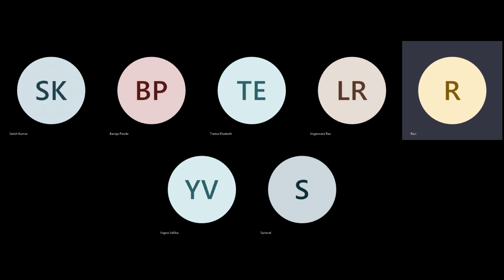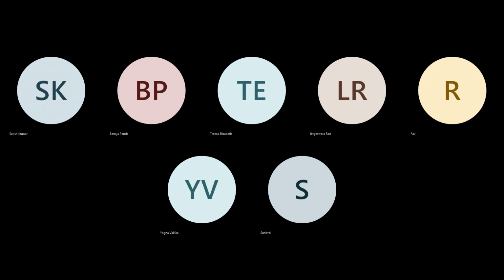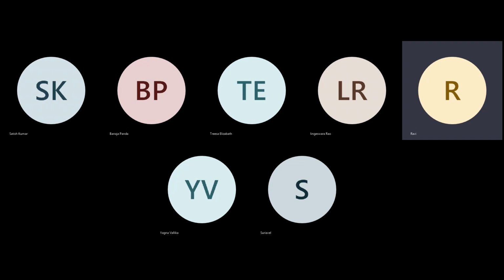Manhattan means exactly between this point and this point, how much is my rectangular distance? That's the Manhattan distance. Your route can go all around the place, but that is a different thing. What is the shortest routable distance? It cannot have a diagonal straight line, right? It has to have horizontal and vertical. That is called Manhattan. So in that, what is my shortest distance?